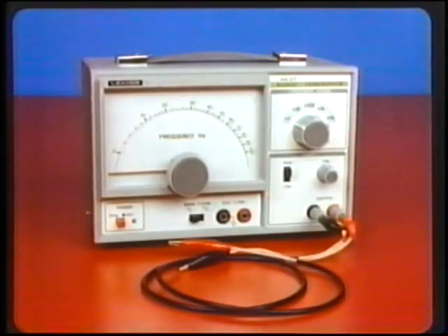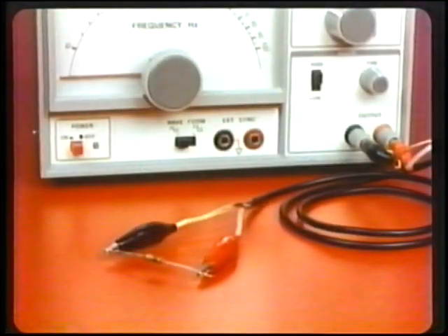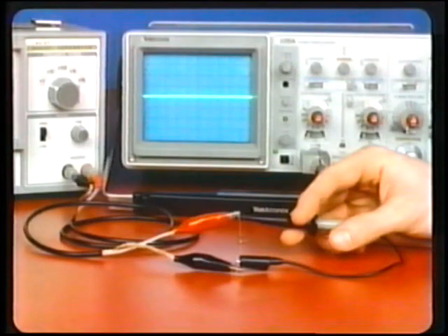Now that you know the oscilloscope and probe are functioning properly, it will be necessary to obtain an AC source. In this example, an audio generator will be used. The output leads are connected from the audio generator across a 1,000 ohm resistor to create a load. Then connect the spring-loaded hook and the alligator clip ground from the oscilloscope probe across the resistor.